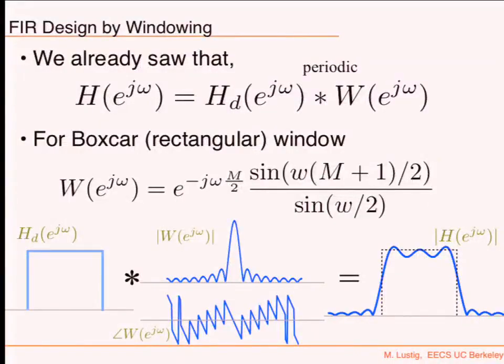It's a periodic convolution between the desired frequency response and the frequency response of the window.